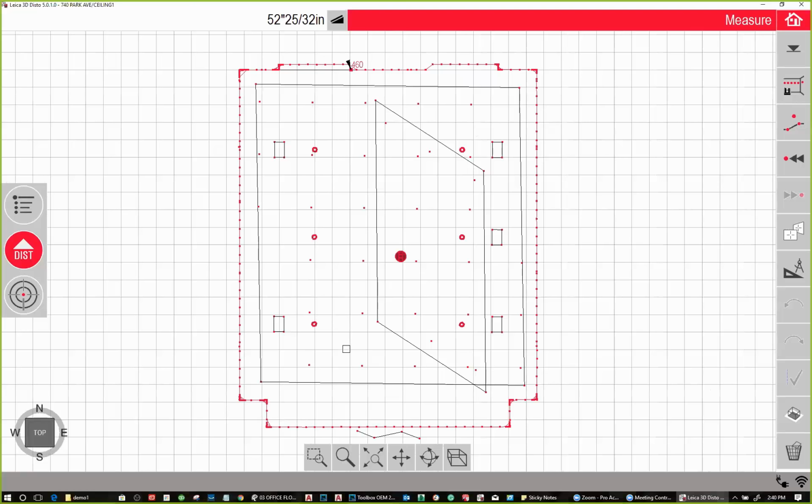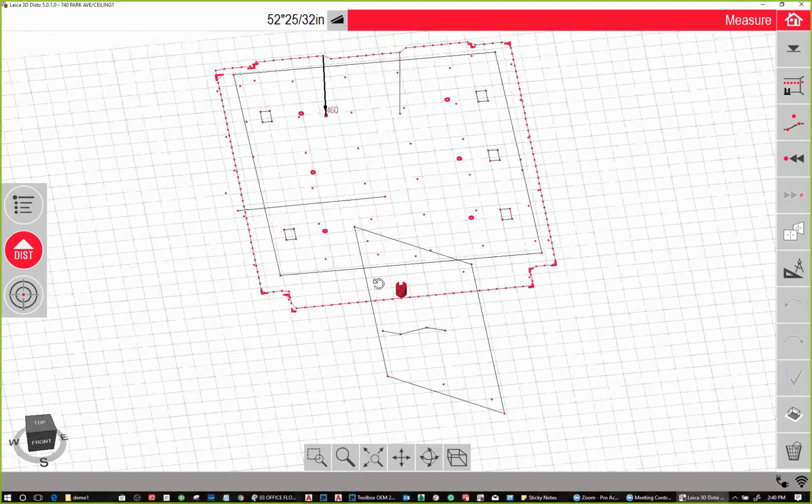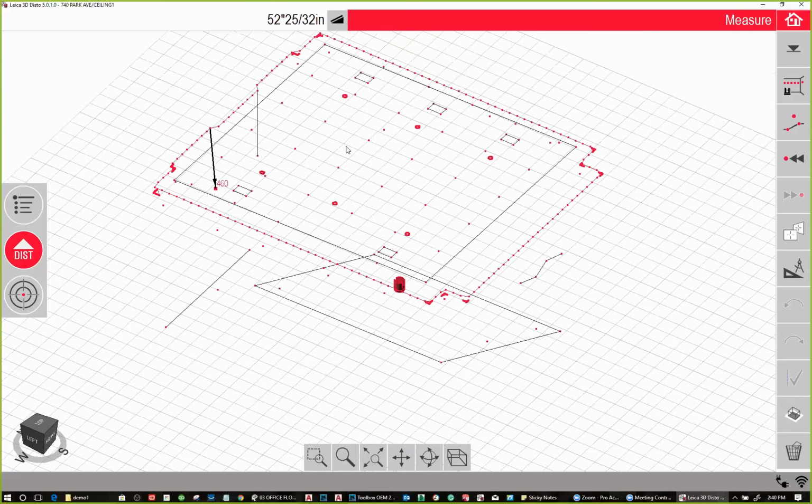And then I did a grid scan, and you can see the points that are just floating in space. In AutoCAD, it puts faint lines in between. But these grids were a grid scan. So I just took a grid scan to see if the ceiling was out of level, so we could account for that in the paneling that was happening there.